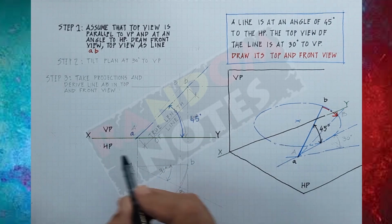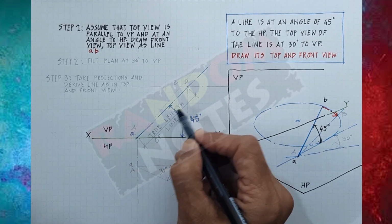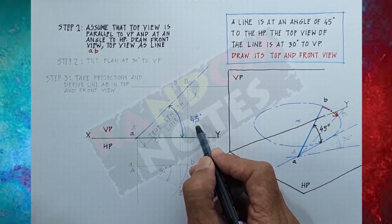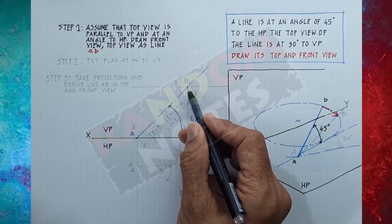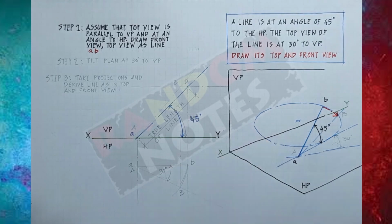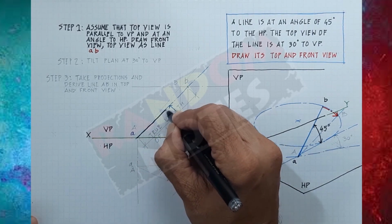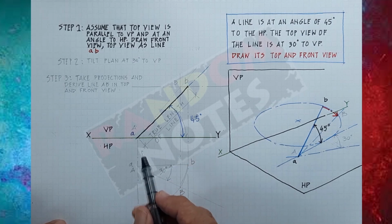On the XY line, I took a random point A. From there, I took a reference line at an angle of 45 degrees. On this, I measured the true length of the line and then I made the front view. This is the front view of the line. Let us name it small a, small b.